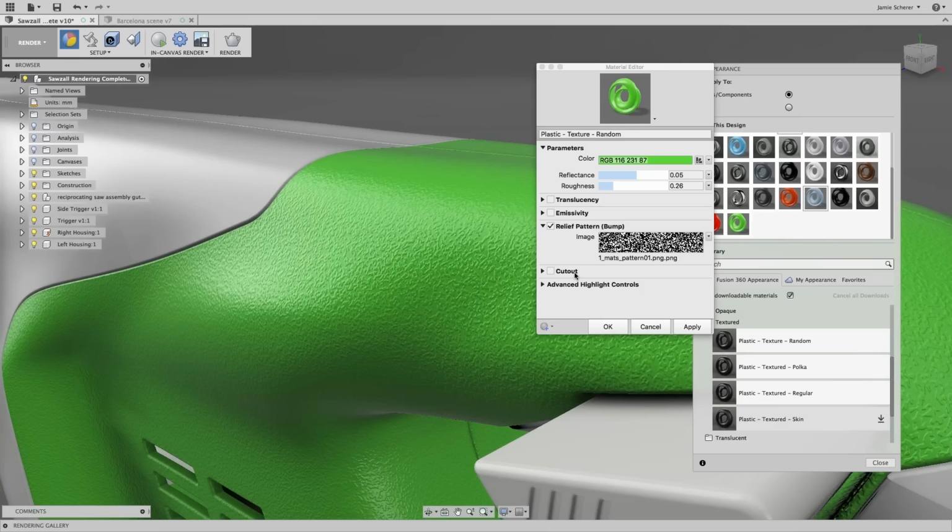Or the mesh on the front of a speaker, an earbud, or something like that. Perfect examples where adding all of those holes is very computationally expensive. It takes time if you do a lot of patterns. We can essentially fake that with a cutout material, which is another great way that we can fine-tune our designs in Fusion.